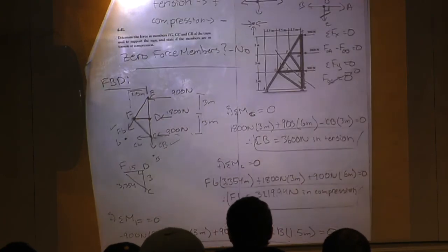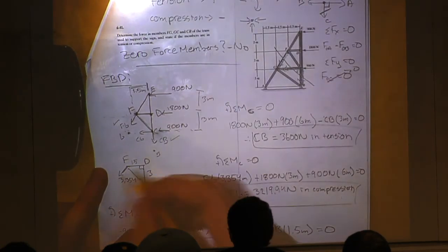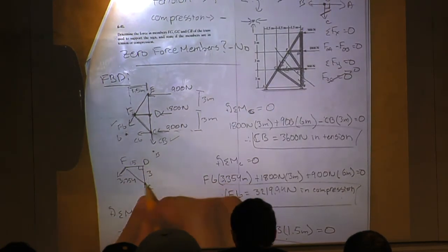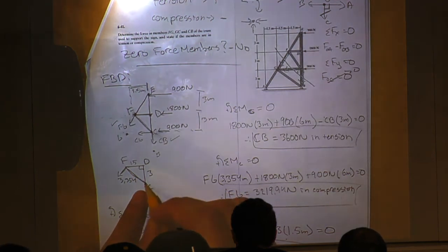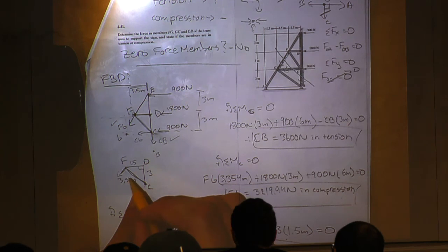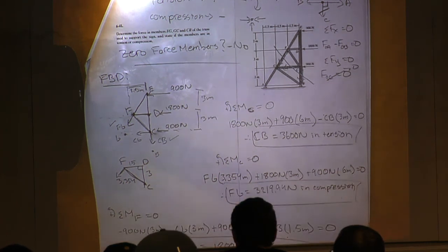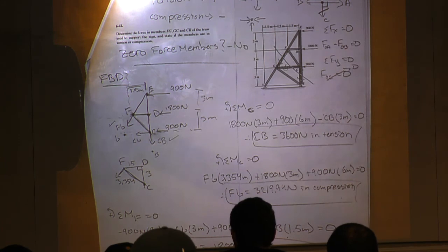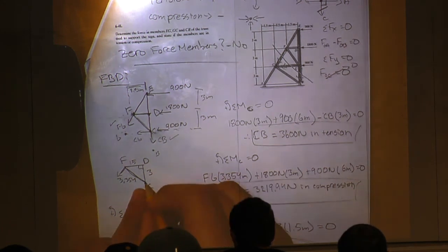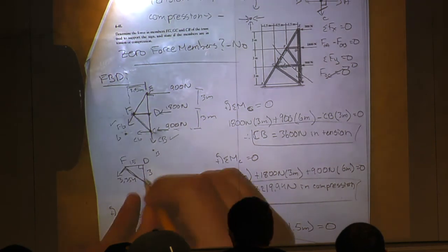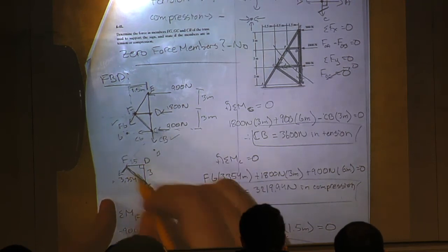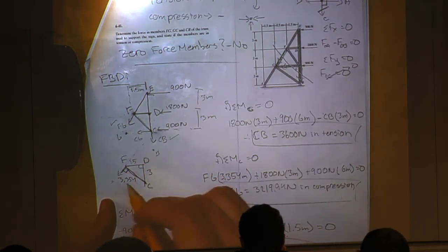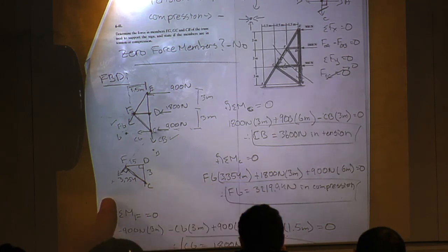Okay. So you need a force times a distance. In this case, I have a perfect perpendicular distance from the point about which I'm taking my moment to the force. Theoretically you can take any distance from your moment to your force, and it should still give you the same moment. But in this case, I did a perpendicular distance because I saw that this F was coming along that line right here, and that's perpendicular right there. So I figured if I found this distance, I wouldn't have to worry about the x and y components. I just knew the distance in general.